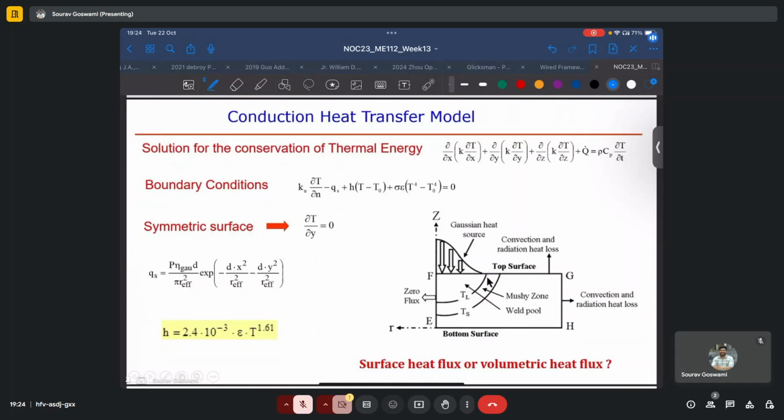Again, just to account for the convective and radiative losses in one term, because as you see, the radiative losses are commensurate with the fourth power of the temperatures. And for discretization of these equations by simple techniques such as finite difference or central difference, the number of terms may become very large. It increases the computational complexity.